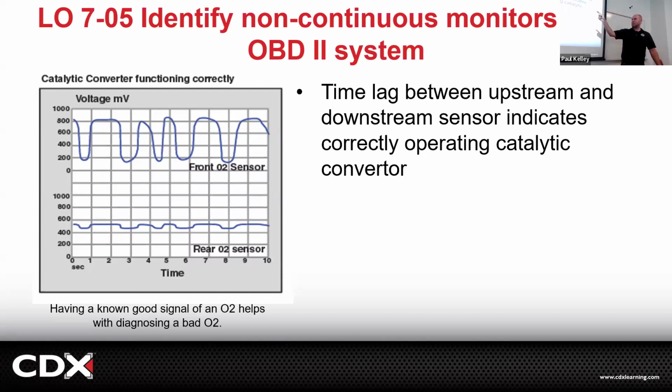But with your eyes, if you're seeing this graph live, you should be able to catch, is it normal or is it abnormal? If you pull it off and it doesn't even really seem to peg it at all, I'd be like, I don't know about that oxygen sensor. Sometimes oxygen sensors get coated with contaminants. And then, yeah, there's a whole bunch of oxygen in the exhaust, but it can't really sense it because it's coated with junk. And then you'd be like, I don't think this O2 sensor is good. Cool. But this looks reasonable. And this looks actually really reasonable.